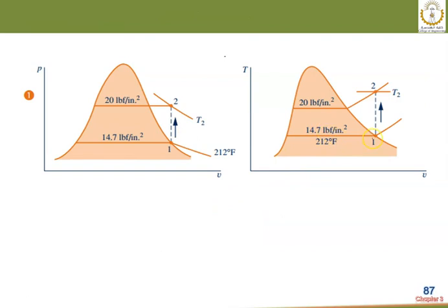So what we have, we start, neglect this, okay? This is the TV diagram. We start at saturated vapor. Since this is a rigid body, the volume is constant. This is pressure P1, and P2 equals 1.5 bar. So state 2 will be here, and it will be superheated.